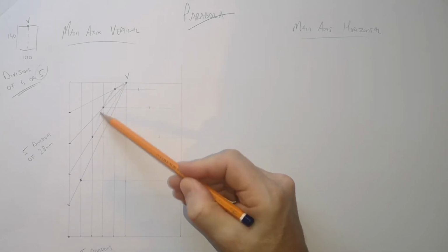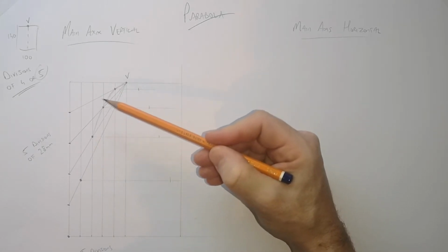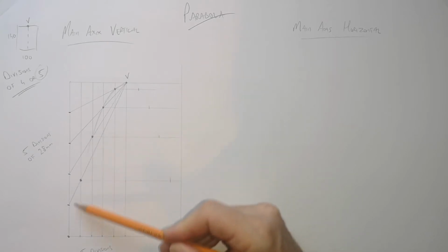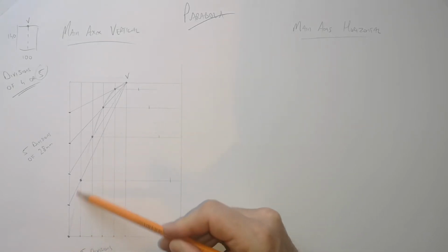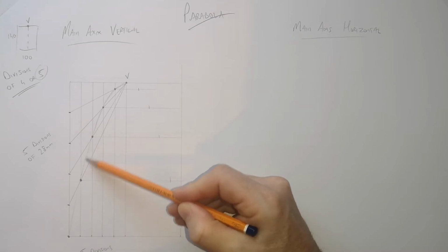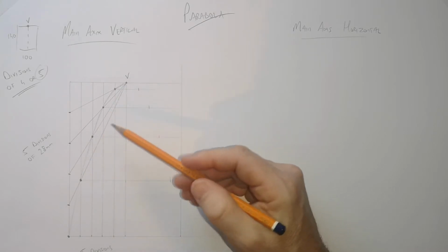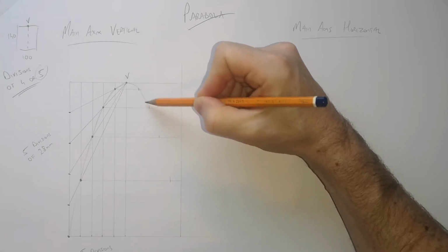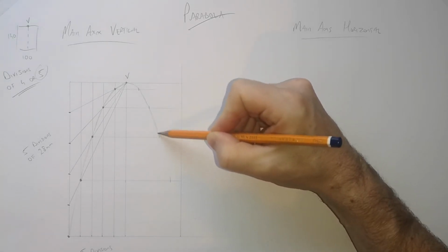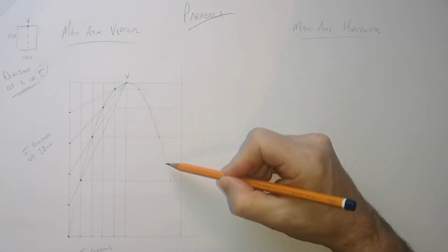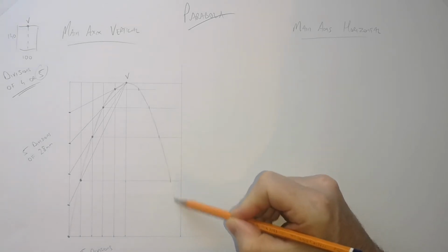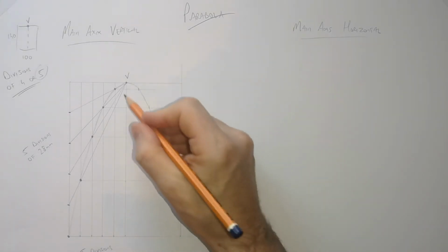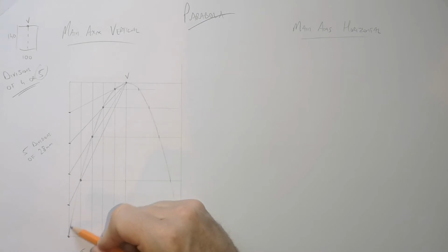Now, if you want, on a nice big drawing like this, see the way I'm holding the pencil all the way down here? This will give me a nice big sweep, and it's often easier for drawing the lines kind of straight. So I'll do it kind of lightly like this. Get around here and try and get the shape of it. And once I can see where it's going, it doesn't matter if I make a mistake at this point. Then I can go back and go over it heavy when I know where I'm going.